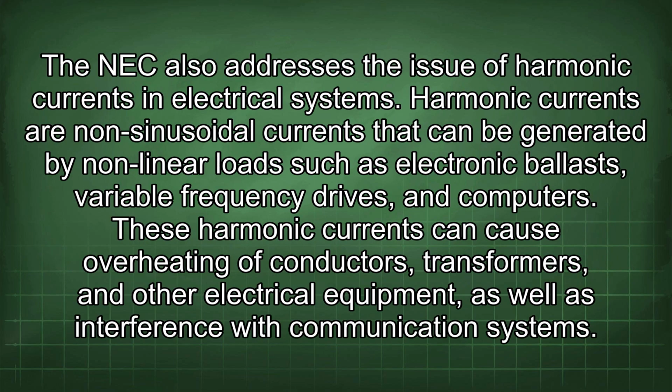The NEC also addresses the issue of harmonic currents in electrical systems. Harmonic currents are non-sinusoidal currents that can be generated by nonlinear loads such as electronic ballasts, variable frequency drives, and computers. These harmonic currents can cause overheating of conductors, transformers, and other electrical equipment, as well as interference with communication systems.